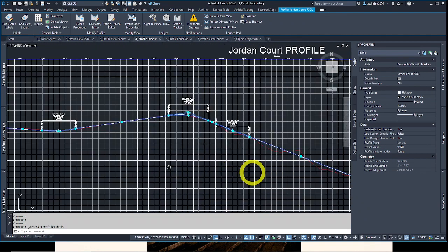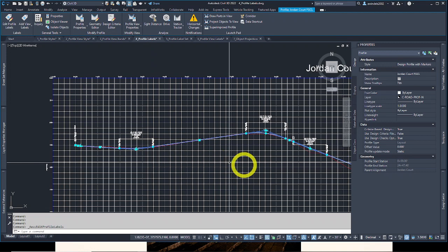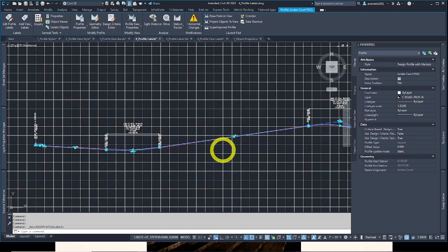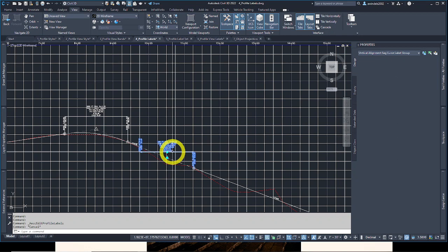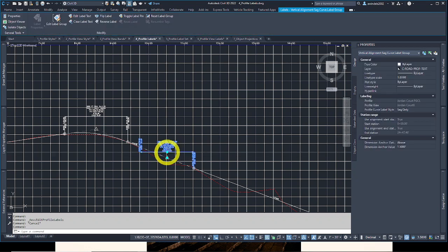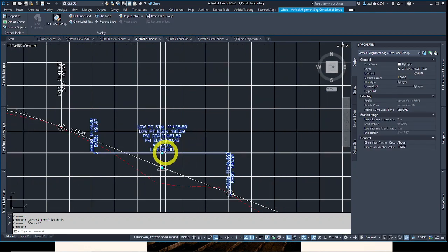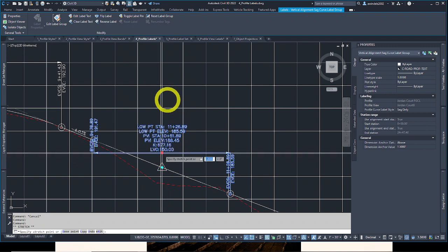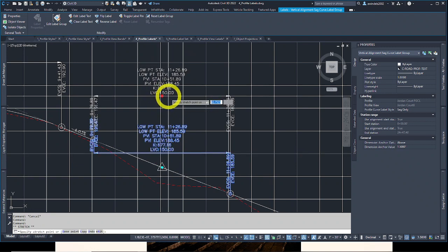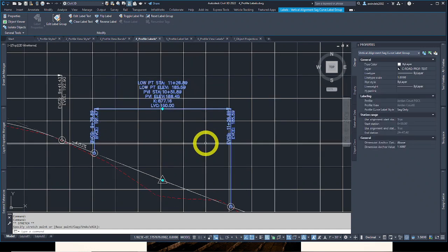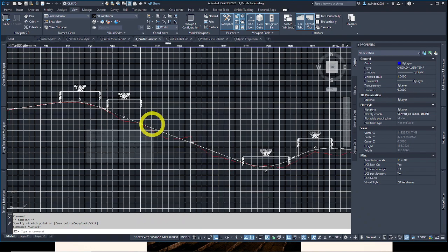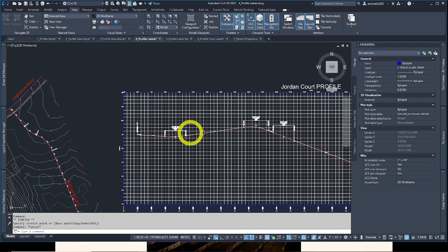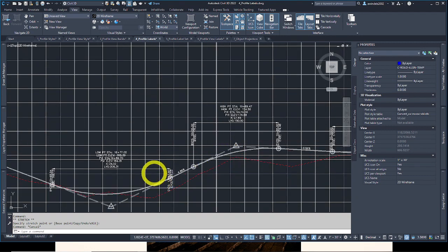Zoom in to the third curve label from the left. So from the left, 1, 2, 3. You can kind of see it didn't grip. They don't always come in the perfect spot, but we grab this curve label of the profile view that has grips. This one will move it upwards so it's more readable. There we go. And we applied all these labels to the entire stationing of this whole profile. You can do it for specific stationings. We didn't have a need to do that.